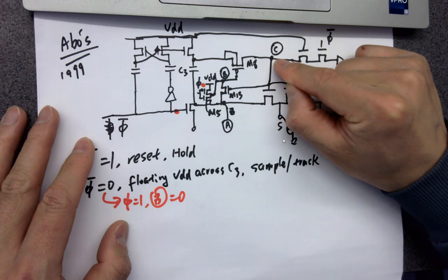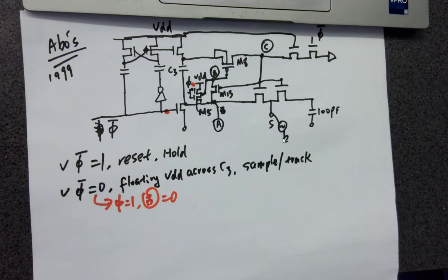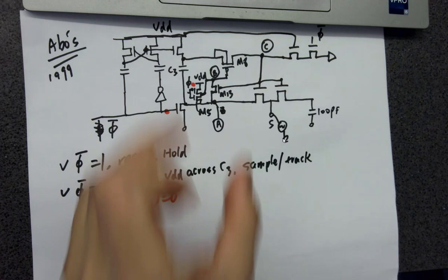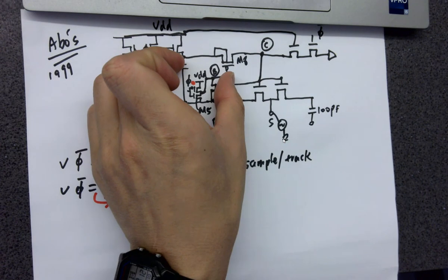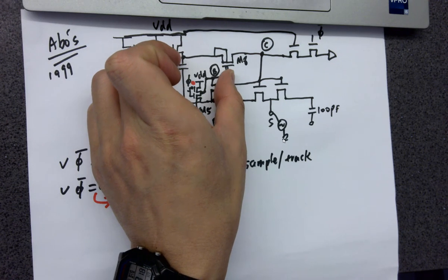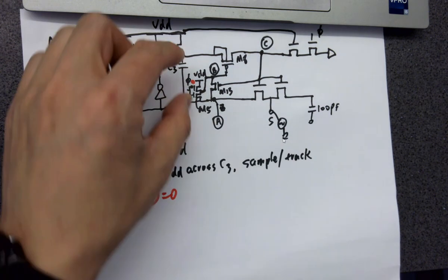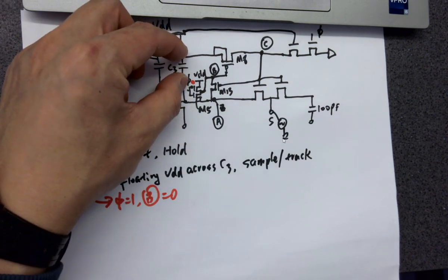So C is VDD. Now, it's like a floating VDD is being applied to the VSG of the PMOS to turn it on. Over here. So what's happening is now you already have a VDD being added to it, and now it's trying to push this VS to that DC voltage VDD.